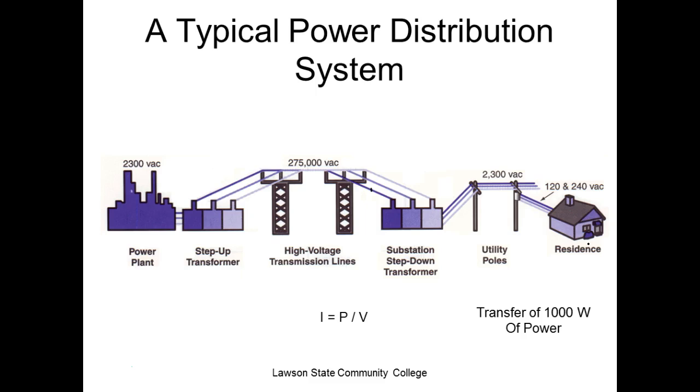So this is just an analogy right here. Here's my house. We have two voltages, 120 and 240. Of course, y'all are going to vary. What I'm doing over here is turning on a load that's designed to run at 120 volts, 1,000 watts. What does my house need? It needs 8.3 amps. Okay, that makes sense. And what would be the wattage? It would be 1,000 watts.